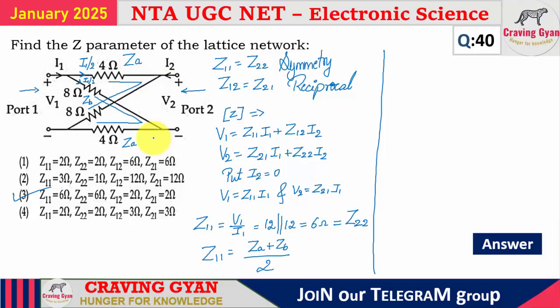Now look at the things. Apply KVL to the output loop. What am I going to get? V2 minus ZB divided by 2 times I1 plus ZA times I1 whole divided by 2, which equals 0. Right? Now look at the things carefully. V2, I'll be taking this I1 term to the denominator, which equals ZB by 2.